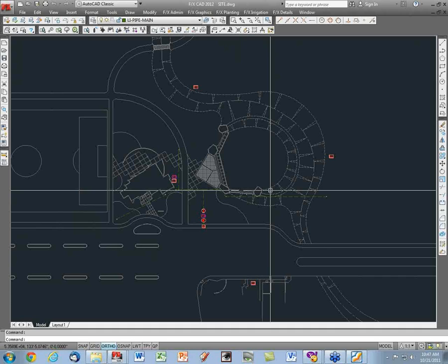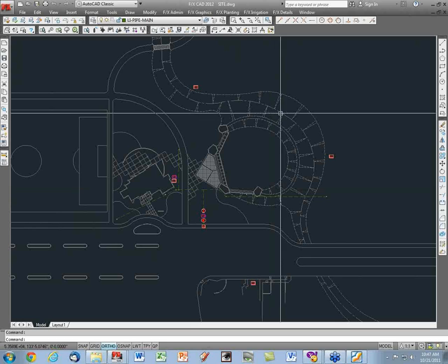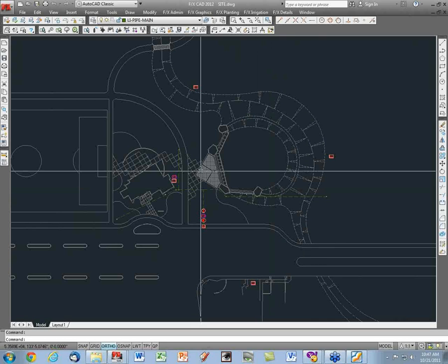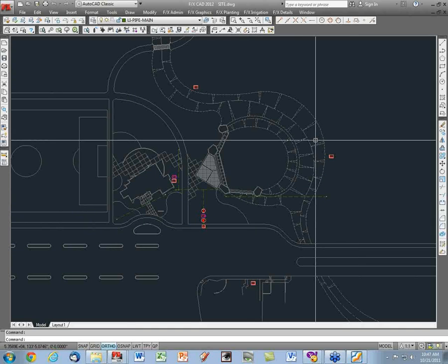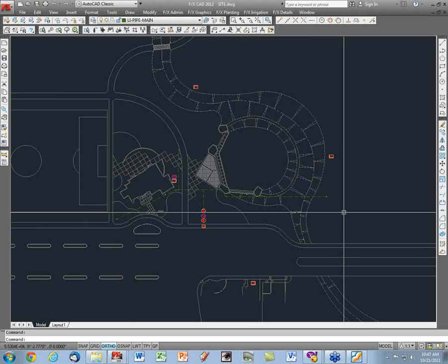Okay, and I would like to note we have up to 2,000 feet of run for these wires. How would you express what the difference? You've got these way out in the field here. How far can you get from your flow sensor to, let's say, these various controllers here? Well, typically, we use the number 2,000 feet to say that you can go from the flow sensor to the controller or to one of these ISOFlow devices or combiflow devices, and then from that point, it's again a similar 2,000 feet to the longest run.